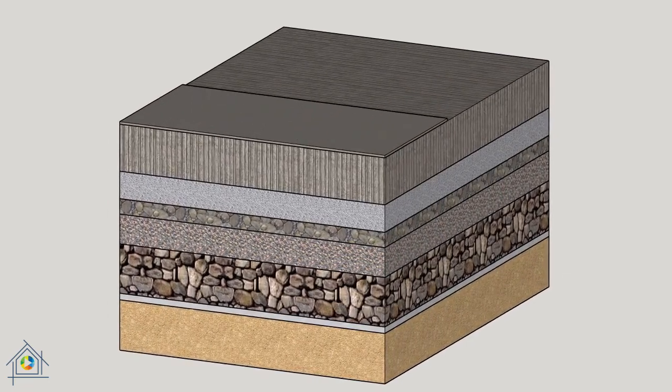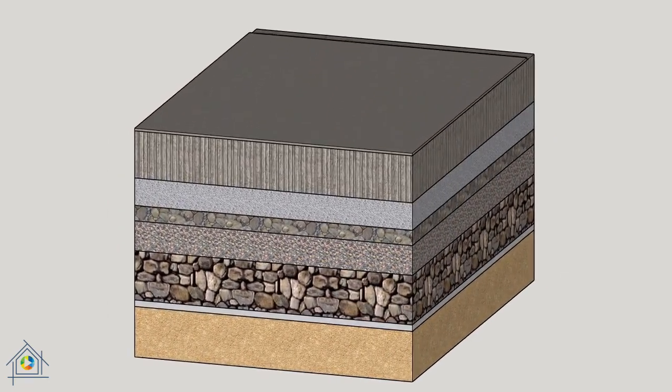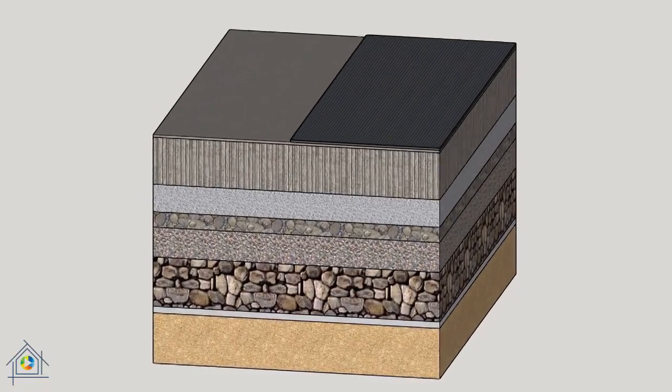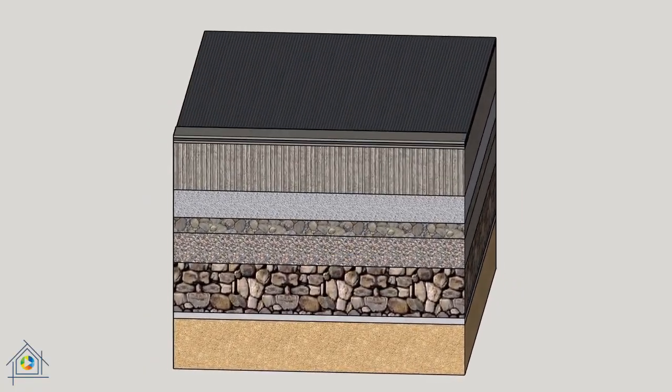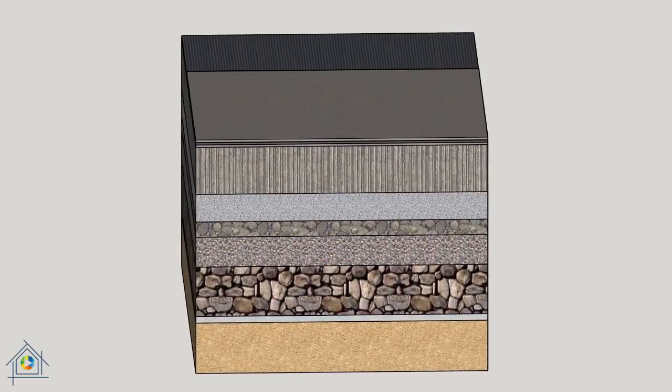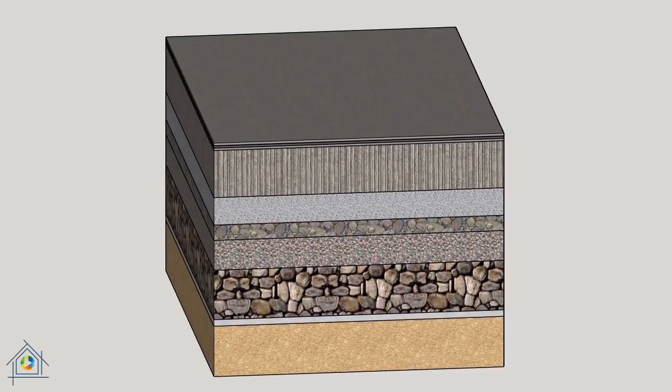The next layer is a moisture insulation that is applied between 2 layers of sand and cement mortar. The moisture insulation layer can be tarpaulin or prefabricated moisture barrier. The sand that makes up the cement sand mortar must be fine so as not to damage the moisture barrier. The total of 2 layers of cement sand mortar, in addition to smoothing the surface, also protects the moisture barrier. The thickness of the moisture barrier layer and mortar is at least 4.5 cm.